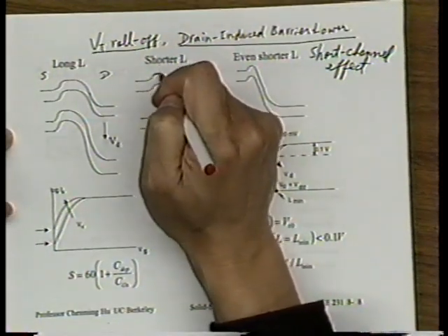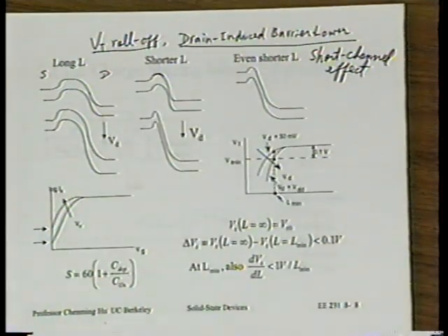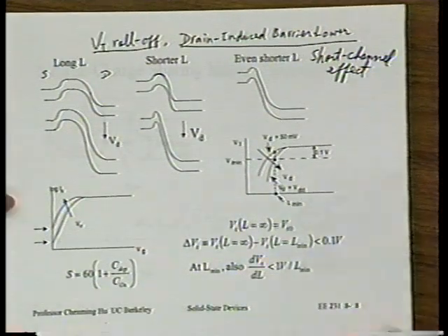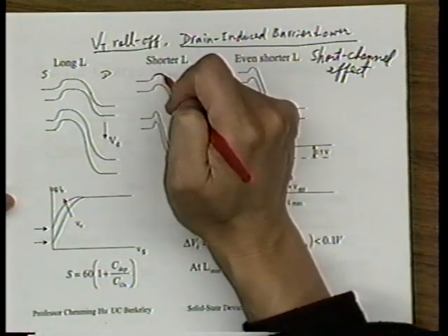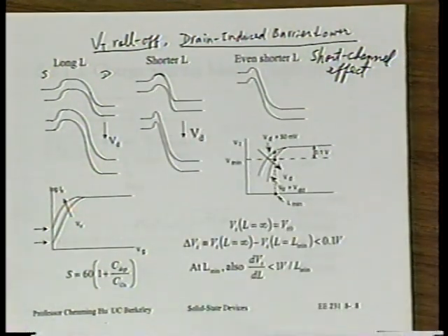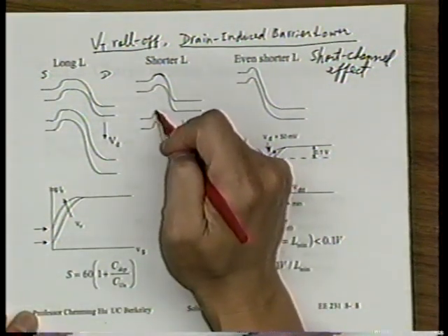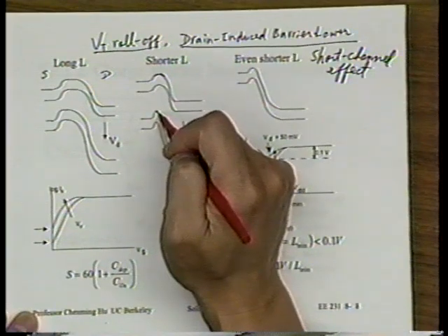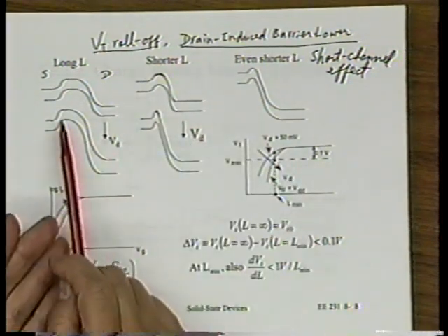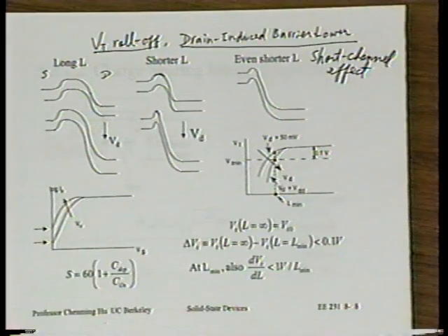We still have a pretty well-established barrier before we enter the regime where the energy band diagram drops toward the drain. And if we apply a certain VD, we probably will still not reduce the barrier compared to the original barrier height. Of course, there's the intermediate region. I'll come back to it, but you will see what I'm trying to get to after I tell you the third case.